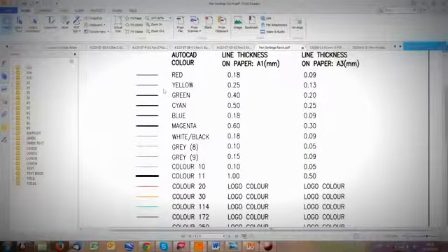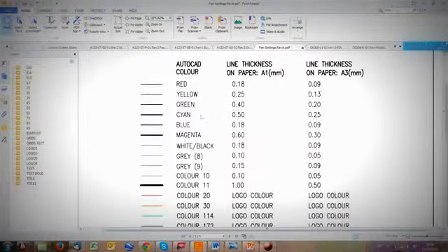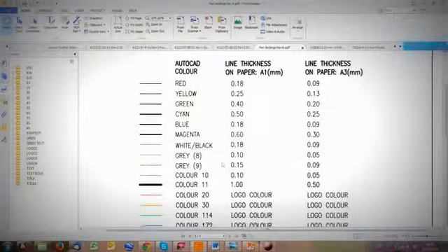So you'll see when I create a drawing or PDF from what we were looking at, red just comes out black, and yellow and all these colors come out black, but with different thicknesses. And you can use those thicknesses then to emphasize or not emphasize certain things.